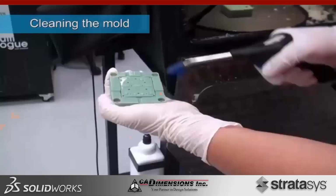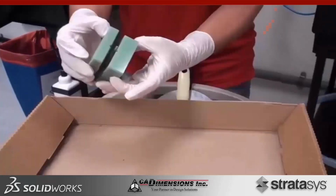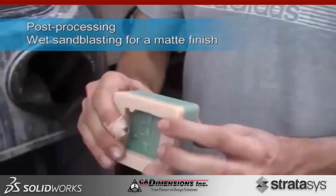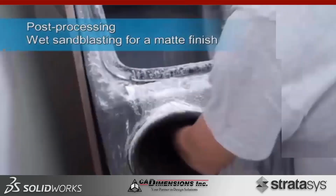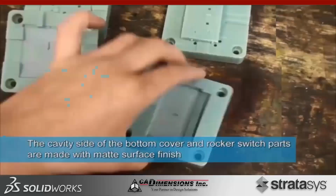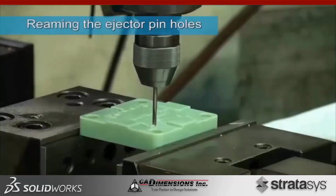shot cycles out of this. So the number of shots that you get out of each specific mold is extremely dependent on what you're shooting in specifically, and more importantly, injection pressure. Injection temperature isn't necessarily an issue because these photopolymer materials are thermoset, meaning that they will actually catch on fire before they melt and lose their geometries.